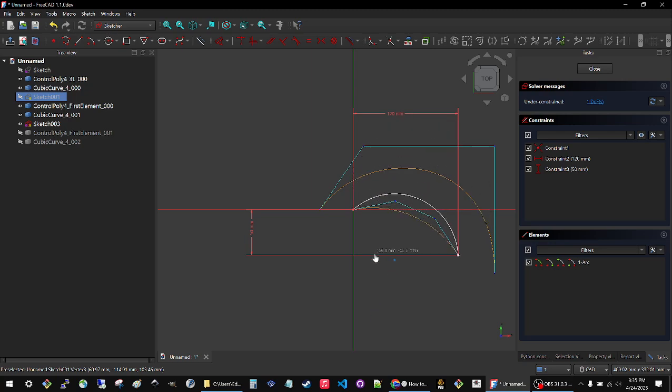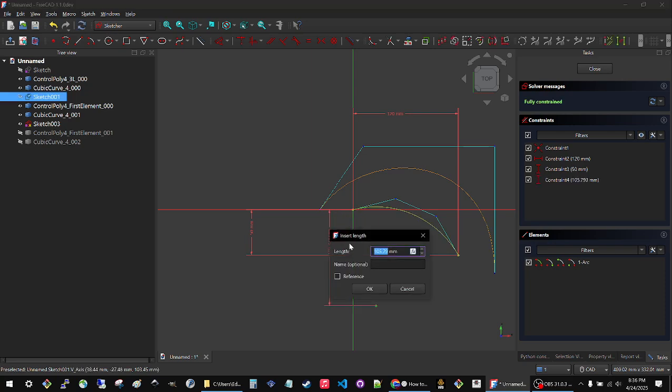Let's grab this guy. Oh, I want to flip it around. I can't do it by dragging the center, but I can. Oh, no, it doesn't let me do that either. Oh, that's a bummer. What I was trying to do was get the center point over here. You know what I can do, though? I bet I can make it flip if I dimension this guy vertically. And right now it's 100. I'm going to make it minus 100.